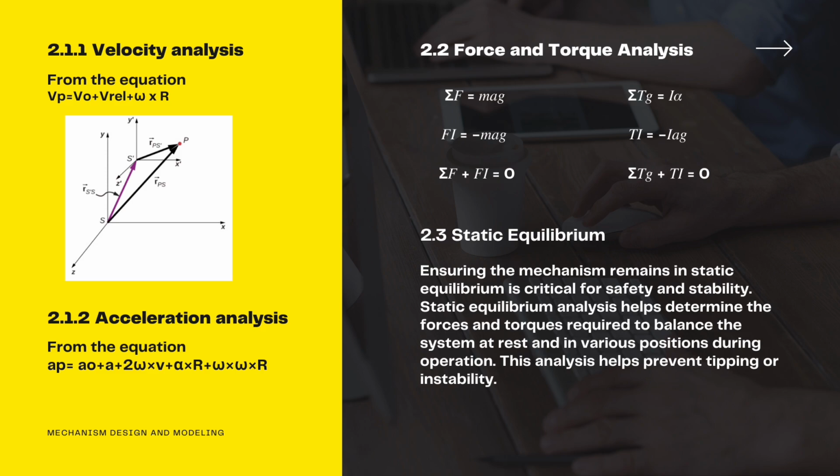In force and torque analysis, we use Newton's and D'Alembert's equations of motion to calculate. D'Alembert's principle is an extension of Newton's equation, by treating inertia force and torque as acting in a direction opposite to the acceleration and angular acceleration. In calculation by using superposition, we use the hypothesis of no friction in the mechanism. The forces calculated, to make a mechanism that has mass and inertia in each part, will be combined and will have the same effect as the normal calculation.